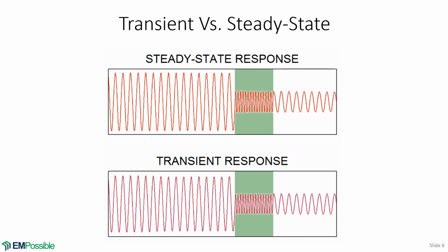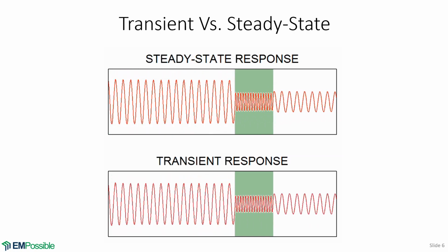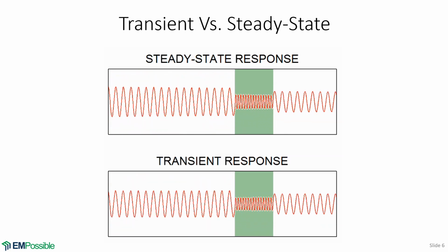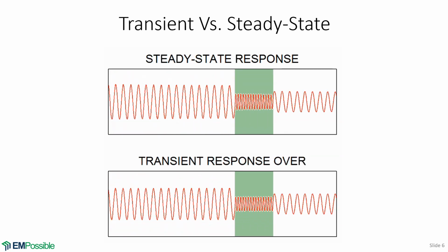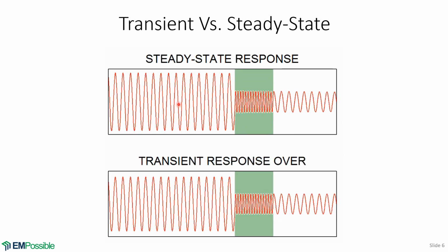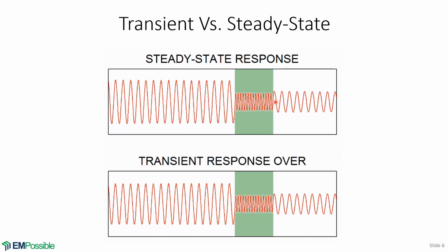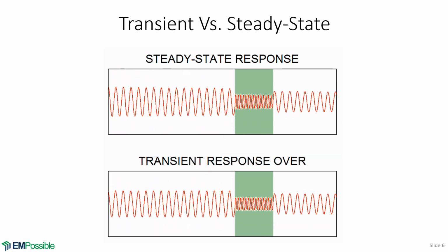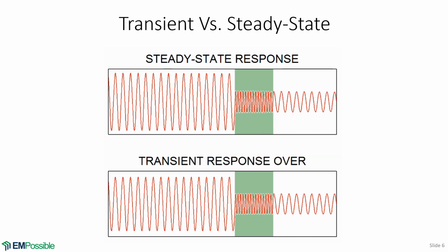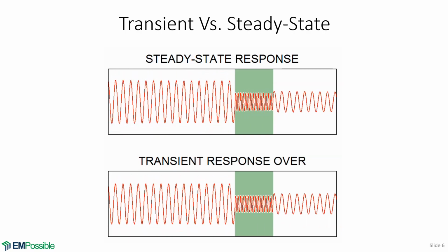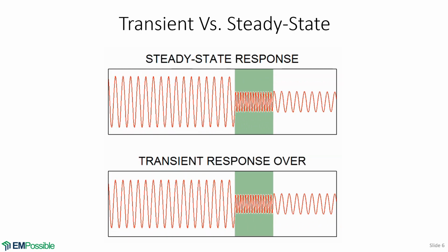After some duration of time, it matches exactly what's at the top. Now, if we use a frequency domain simulation, that just jumps straight to this steady state response. A time domain simulation, which was down below, shows you everything leading up to that steady state response. And then, of course, you see the steady state response at the end. So times where that transient response is of interest, a time domain simulation is your best solution.